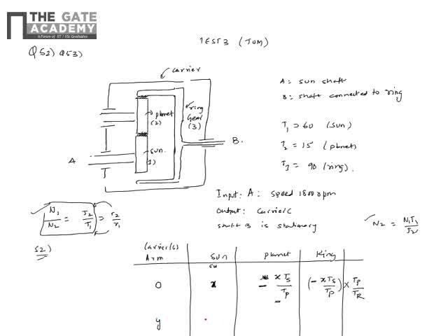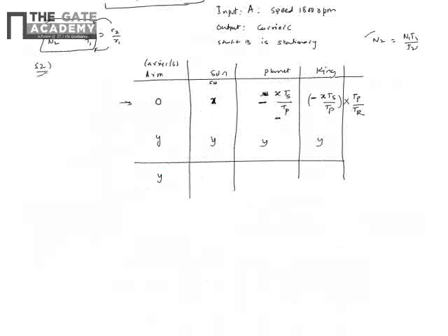Now I give y revolutions. Arm is locked initially, the axis of each thing doesn't change, and it's just a simple gear train. Now when I give y revolutions, it's basically giving y revolutions to all. There is no teeth movement, the teeth are locked, and when you move the arm, everything moves by y revolutions. So when you add these two, you get the total motion.